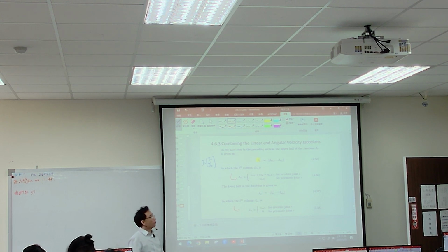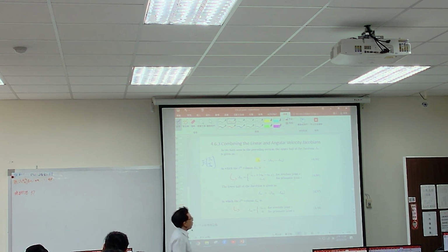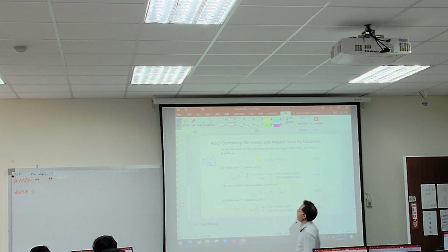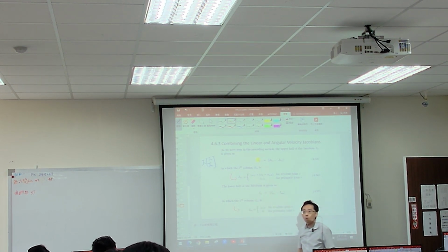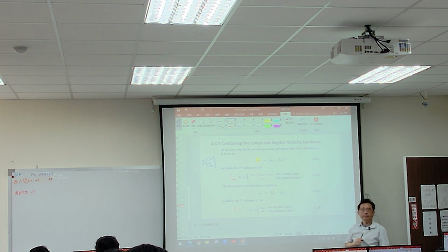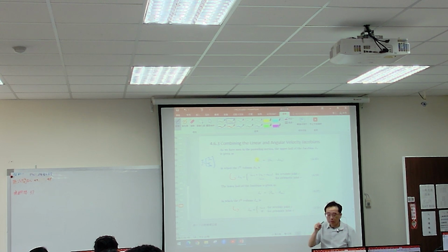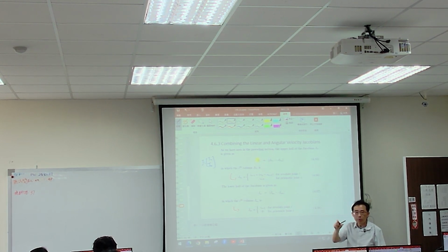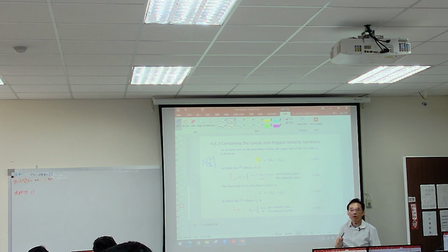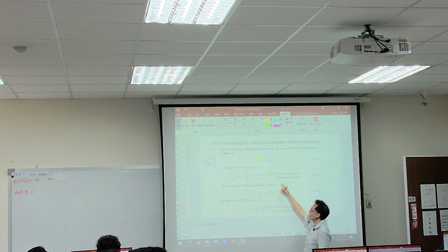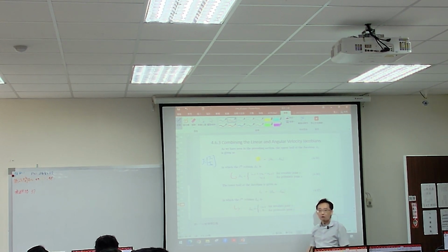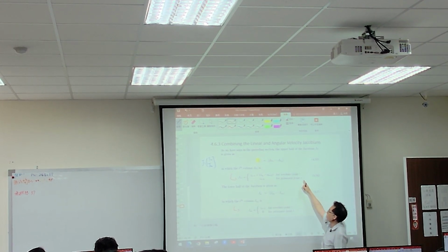For the JV section, if you have the revolute joint i, then you need to provide one of the rotating axes for them, and rotating for what? The length. So O_n to O_(n-1) means from one joint to the other joint. Of course, you can put a different length. If you are interested in some point on the arm, then you put a length over here. So it's a linear velocity for the JV, for a revolute joint.